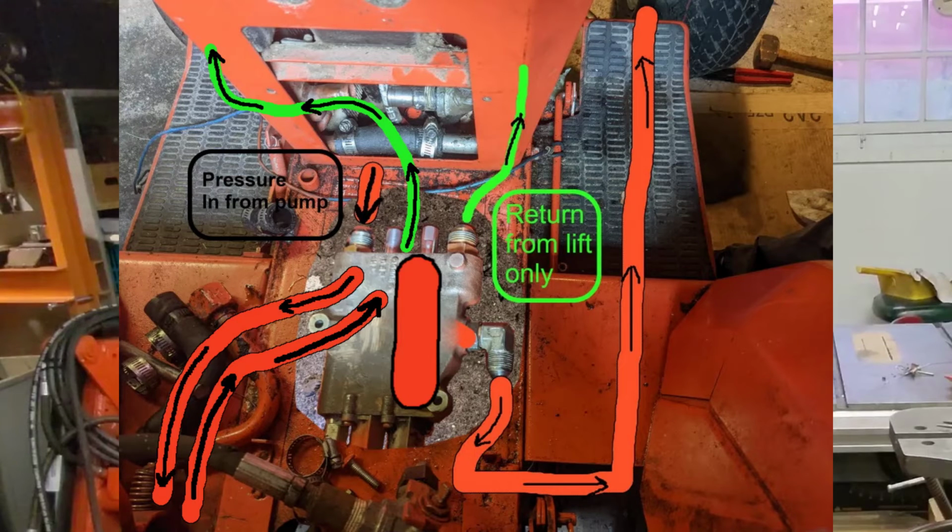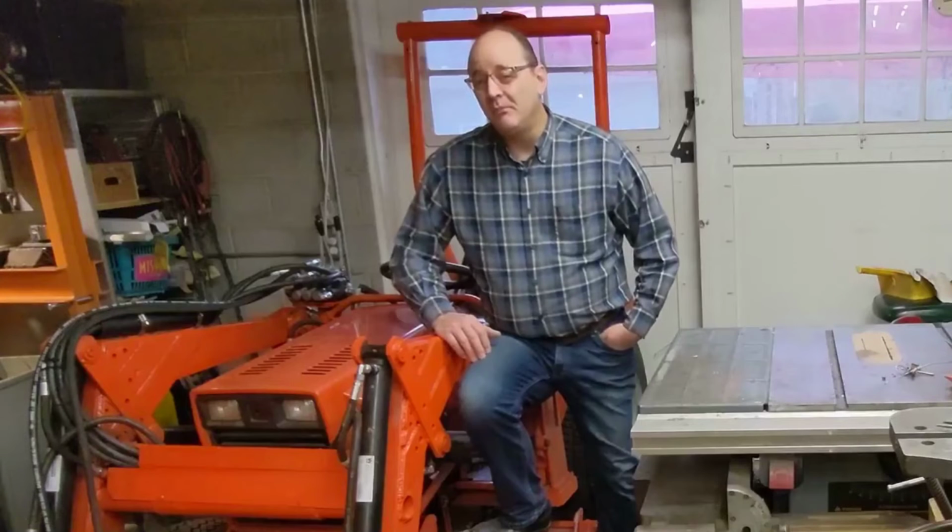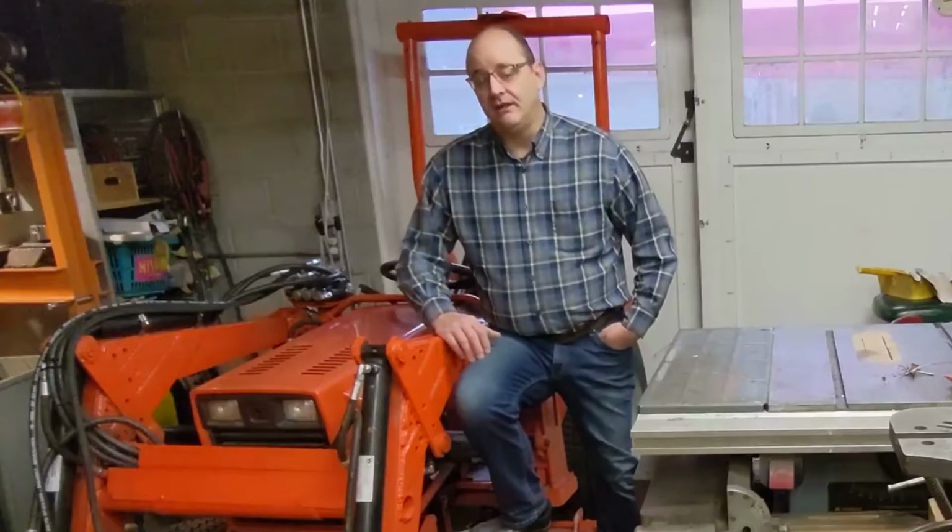With the lift spool activated, the oil will head out one of the lift ports through the lift cylinder and back into the other lift port, and then get dumped into the new return to tank line. So the new return to tank line can be much smaller than before, because all it has to handle is oil coming from the lift cylinder, and only when the cylinder is actually moving. Most of the time, there will be no flow in that line at all.